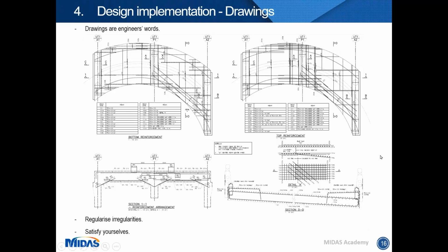Here, this is a cut print of the reinforcement drawing of this bridge. You can see that, as mentioned before, the main reinforcement directions are horizontally and vertically. That is also the global spanning direction of both spans. But you can also see here, there is this area where the global spanning direction is more angled to the piers instead of perpendicular.